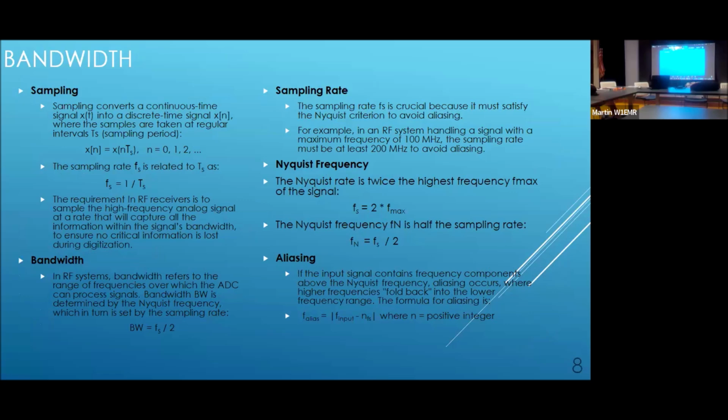Thank you. Okay. So bandwidth. This is something we're all concerned with. You know, how good is the bandwidth on our receivers? And we try to tailor them. Those of us that are CW operators, that would mean not me, but I think Ken is a really good one. So these guys want a really narrow bandwidth of 4 times the signaling rate. So if you're sending your code at 15 words a minute, you're going to want a bandwidth of about 4 times 15 words per minute. That's going to be about 60 hertz of bandwidth.